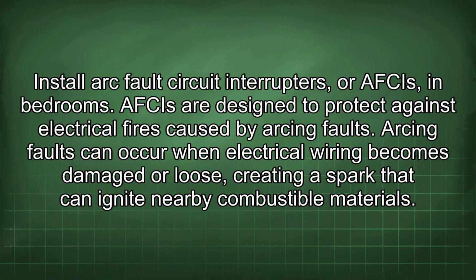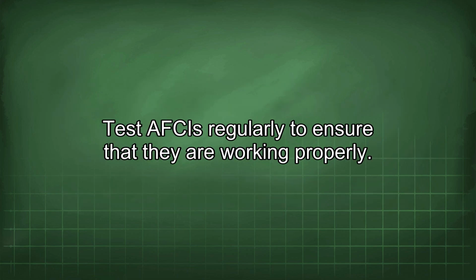Install arc fault circuit interrupters, or AFCIs, in bedrooms. AFCIs are designed to protect against electrical fires caused by arcing faults. Arcing faults can occur when electrical wiring becomes damaged or loose, creating a spark that can ignite nearby combustible materials. Test the AFCIs regularly to ensure that they are working properly.